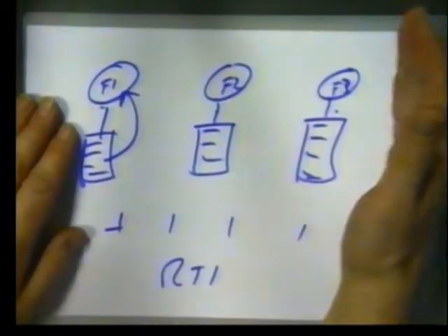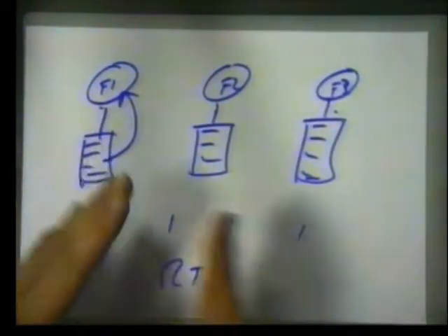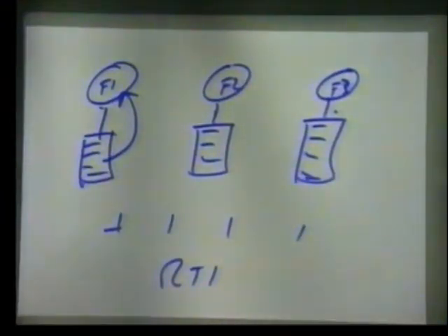With this concept of the stack frame, we could keep on adding more and more functions, and what happens is you get less and less of the processor resources. So the system slows down. There's no guarantee of when any particular function will complete. Such an operating system should not be used in a real-time system.